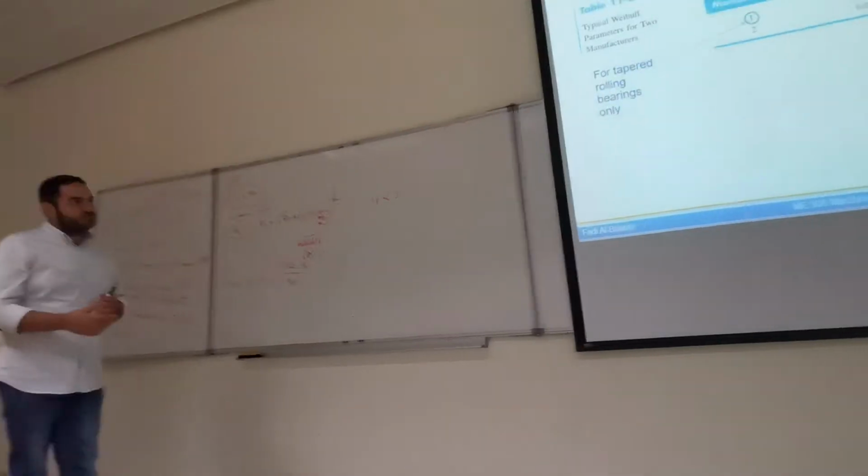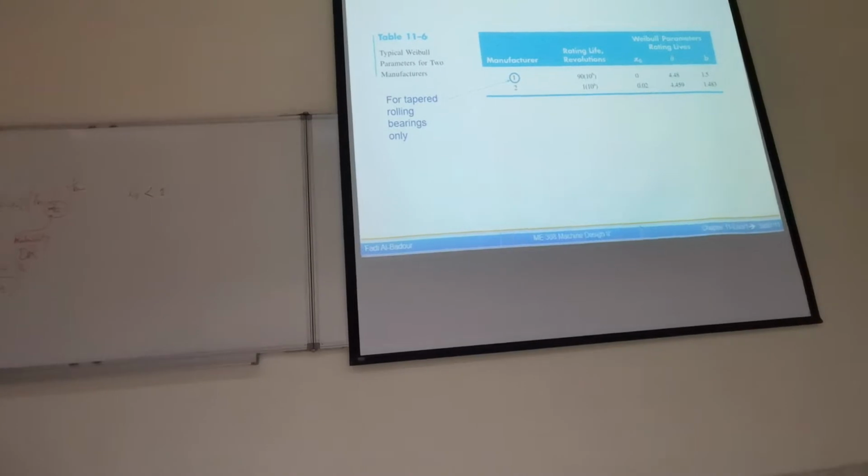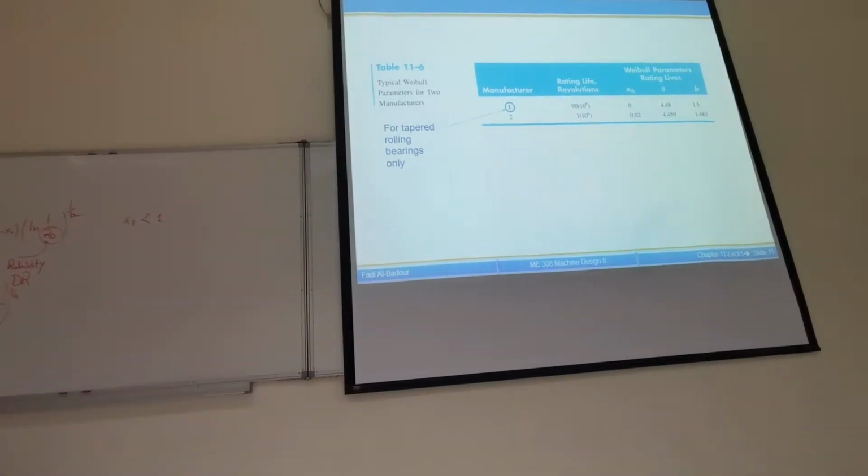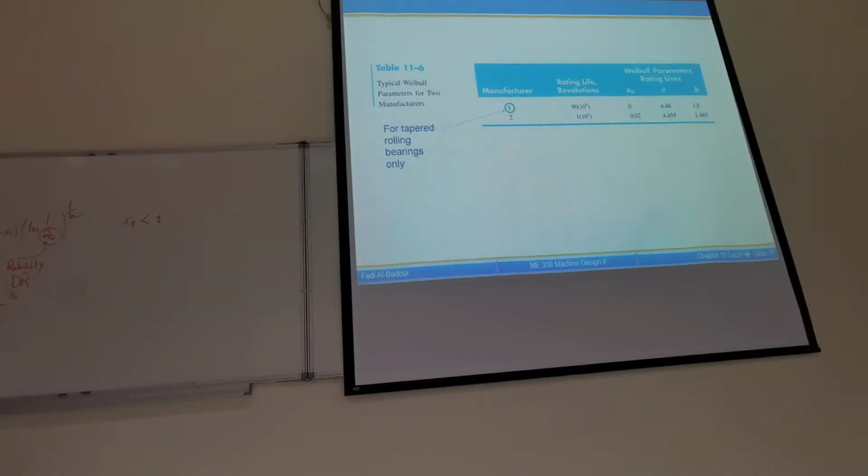Now, for the reliability of structures, based on your design, you can select elements with a given reliability. When we talk about elements, you can select them with a reliability of 90%, 95%, 99%, etc. So every time you are targeting higher reliability, you have to pick the element with a larger capacity, because although you are loading it with lower forces, it has higher capacity, so it's more reliable.